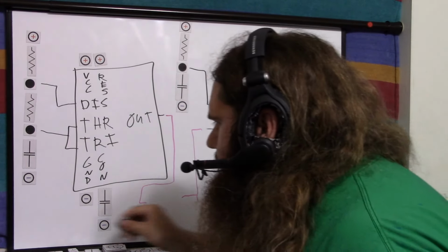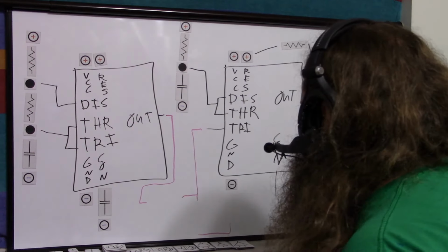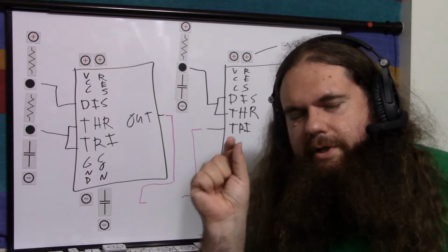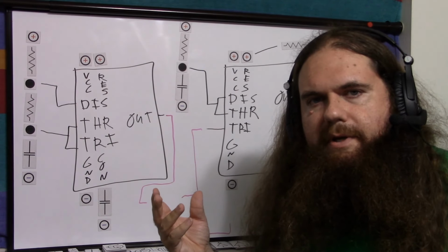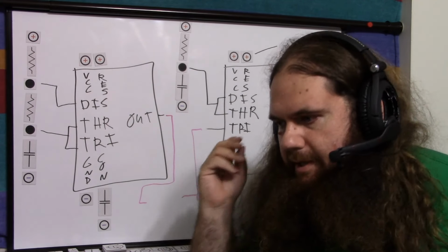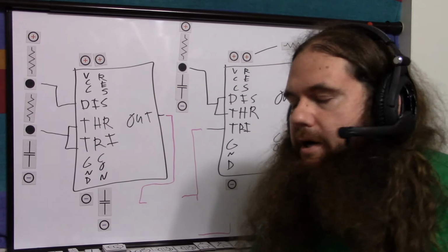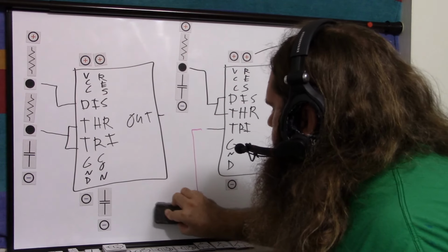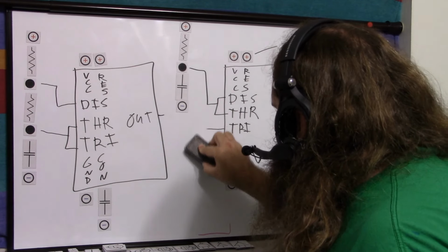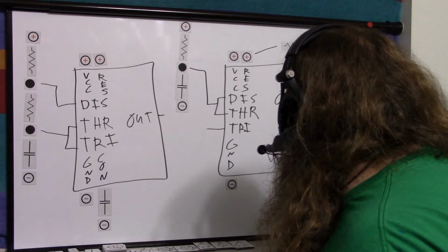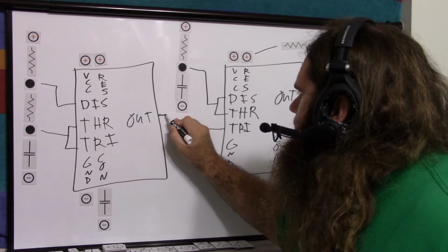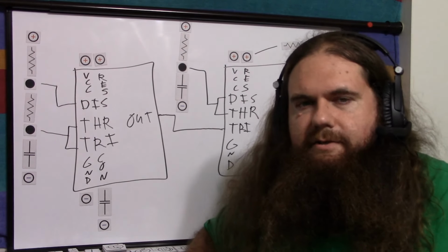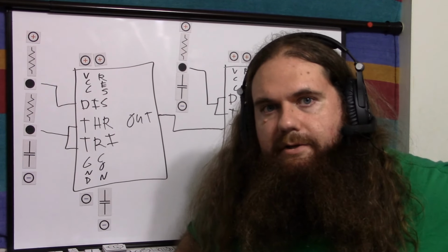Now, why did I deliberately tell you something that I knew was wrong? Learning. It's a good idea. When we want to take a square wave and get really short pulses, the first thing you think of is a high-pass filter. That's brilliant. That's like perfect. That's exactly what we want. But it's fiddly. And it's 2 more parts. You need another capacitor, you need another resistor, and you need more wires, more board space. So it's not the best solution. So forget that. Once I failed to get this working, I realized the internet was making me think too hard.